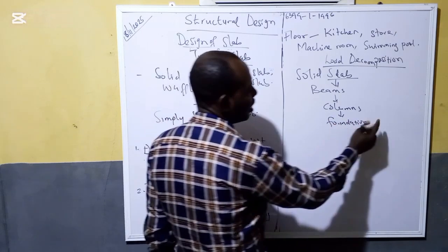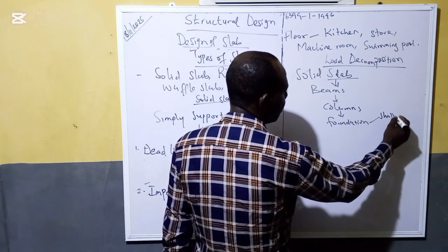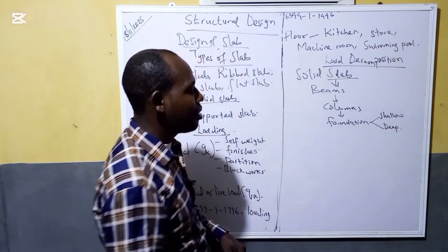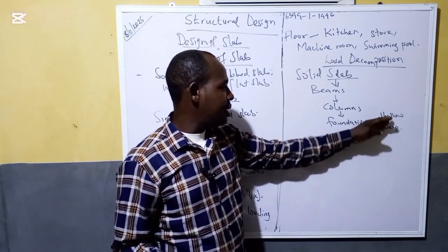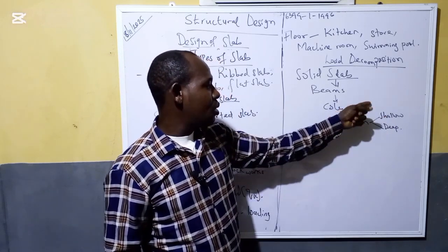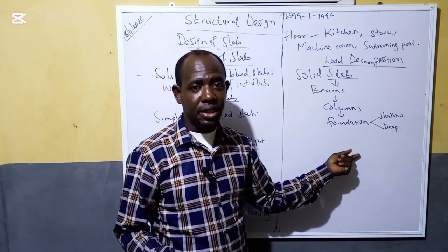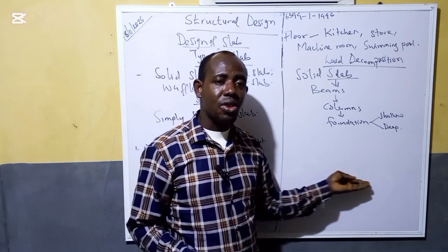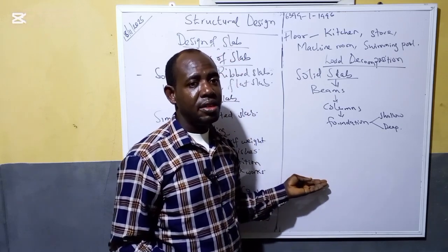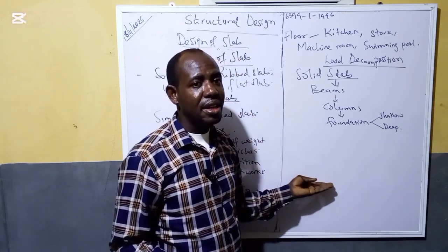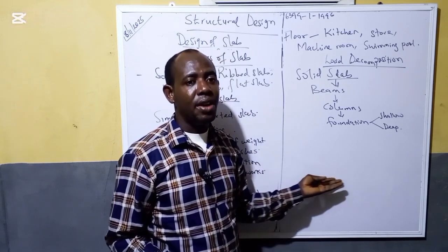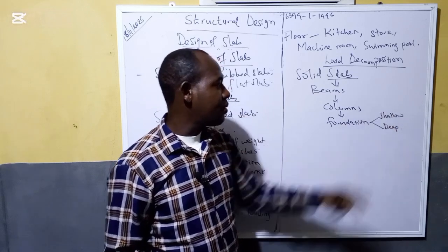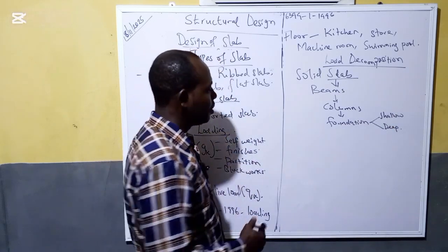Now in this foundation, you want to know, is it a shallow foundation or a deep foundation? What determines this is the load coming on the foundation from the various columns, and also your soil: the soil test that you have done, the bearing capacity, what is the value, is the soil strong or is it weak? It will determine even the type of foundation you use.